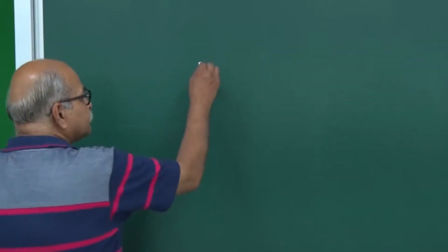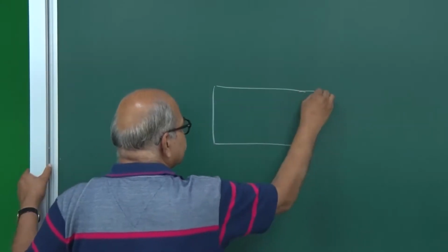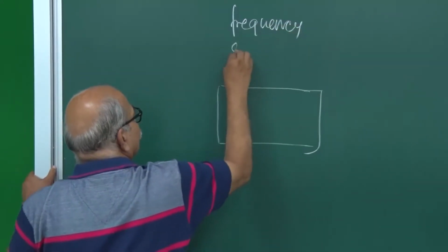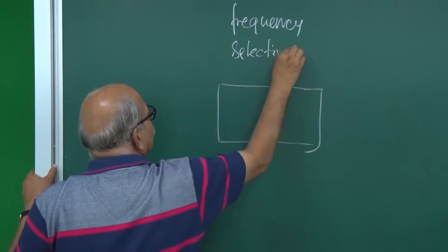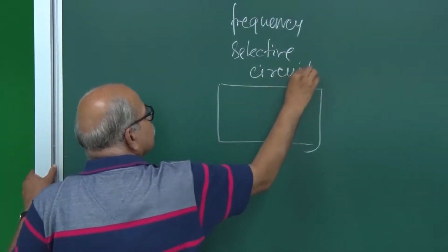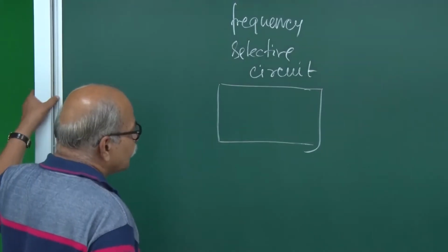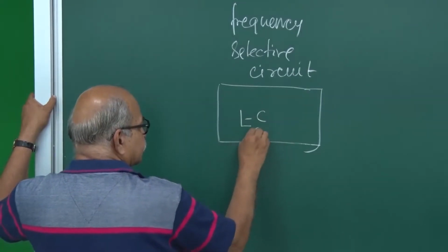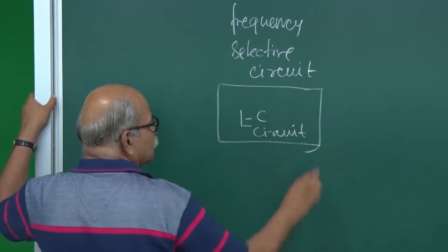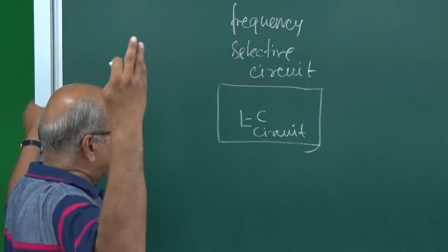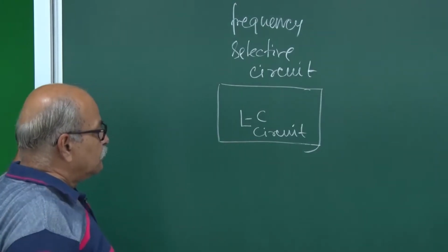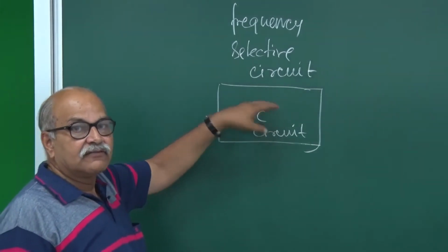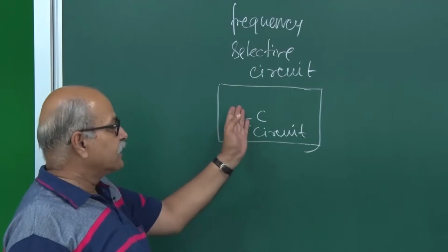The essential parts are that you have some kind of a frequency selective circuit, also sometimes known as frequency selective filters, and what we discussed was this LC oscillations, LC circuit, which is used for several tens or hundreds of kilohertz onwards up to say megahertz. So, that kind of a tuning circuit can oscillate at one particular frequency, and that is decided by the parameters here.